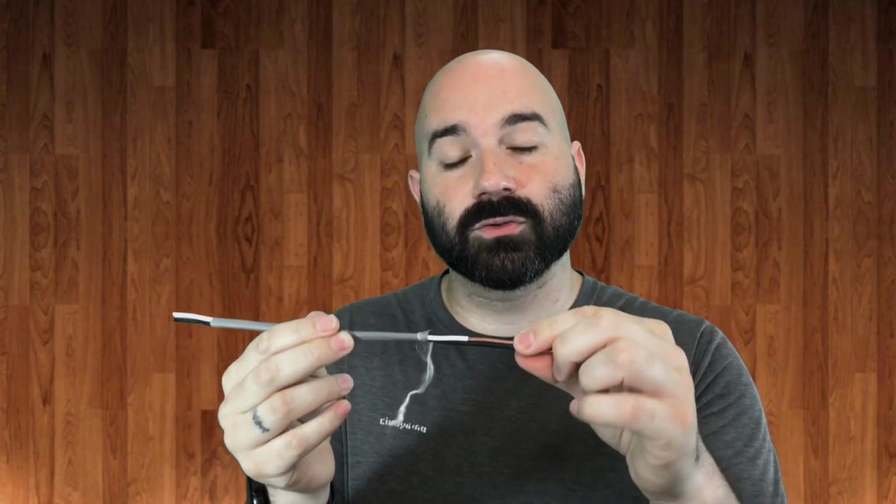The next part of the RC low pass filter is capacitance, or a capacitor. Now, we talked about a capacitor in chapter 2 with condenser microphones, and simply, a capacitor is something that holds a static electric charge. Within the microphone example, there were two plates that held a static charge in between them. But we don't have plates here. We have two conductive wires. But still, between the two, they can hold a static charge when this is a circuit and we have voltage flowing through. And what will make capacitance worse in a cable is the length of the cable. The more surface area you have between the two conductive wires, the greater static charge, or capacitance, that you can have between the two cables.